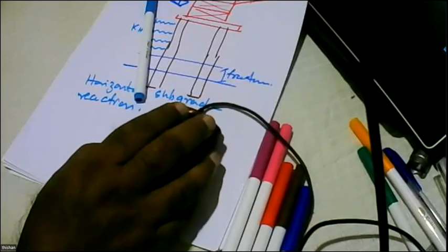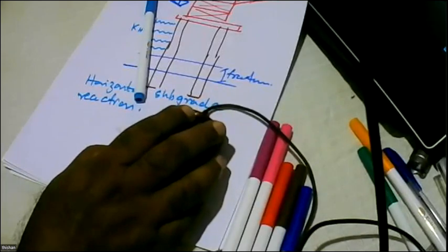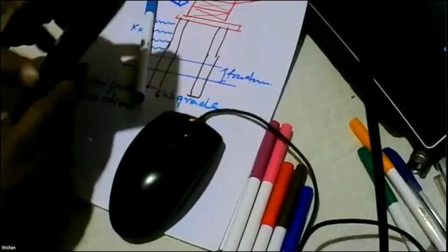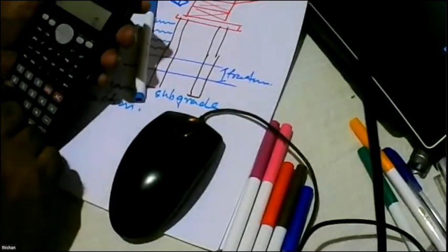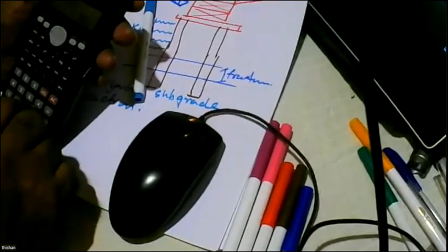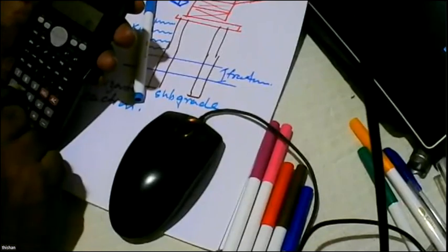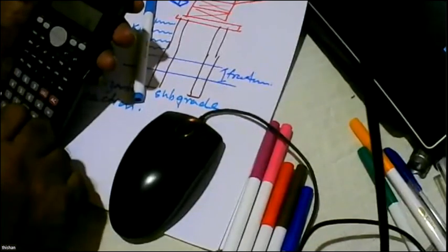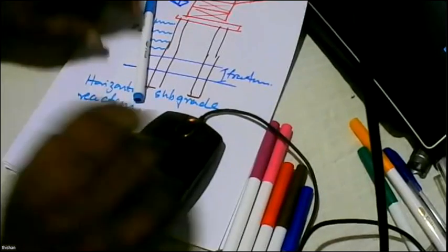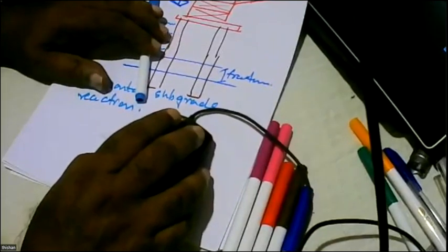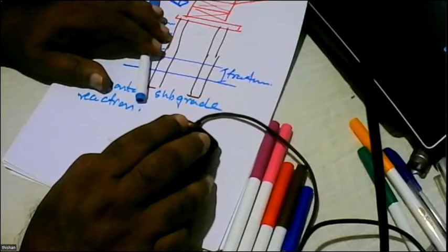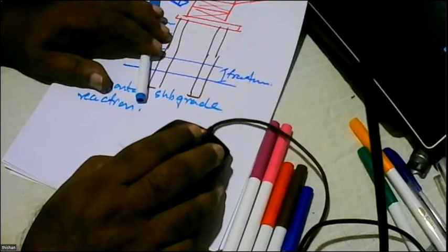Now, let's say we have an SPT of about 15, which means the cohesion of the soil will be 4.5 times 15, which comes to about 67.5. On the other hand, you can also say it's 5 times 15 and use a value of 75. No harm. Because when you look at this, even if you use a value of 5, there are a lot of results falling in that region. But if you use 4.5, it may be even better.